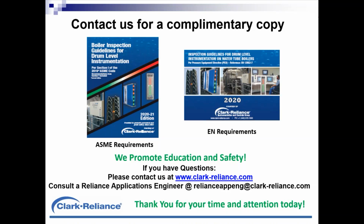And then all those other issues I mentioned about magnetic level gauges in boiler water application: making sure you've got a clean float, and a float appropriate for the operating conditions. If those operating conditions, meaning operating pressure, are going to vary widely, you might want to take a very close look to make sure you're going to get an accurate read on the level.